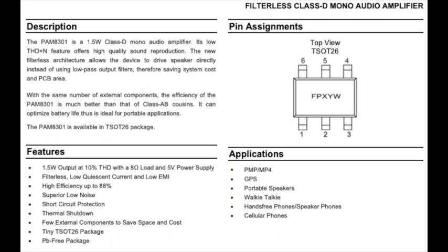And so then I Googled TSOT-26 footprint, and the very first result was a Diodes Incorporated datasheet specifically on that footprint, how it's packaged, how the PCB layout works, dimensions of the package, how the part is on a reel, and all those things. So I gave it no points for PCB footprint and layout, but there is additional documentation if you look for it, but it's not made obvious from the product website.